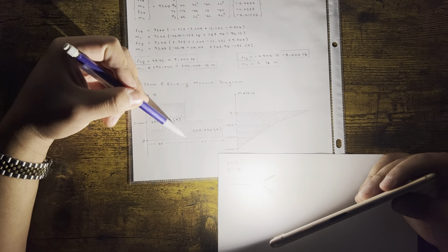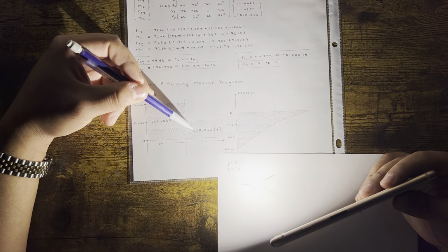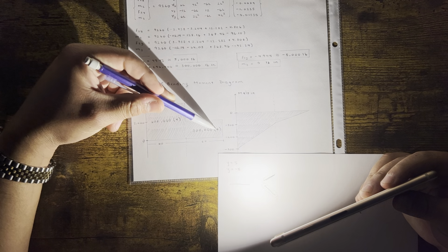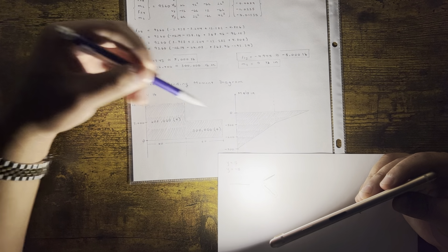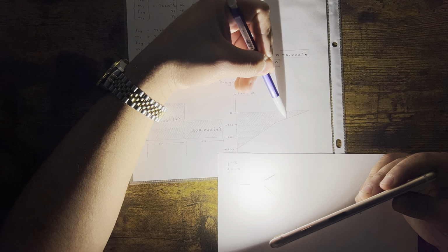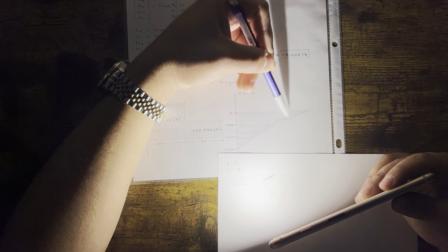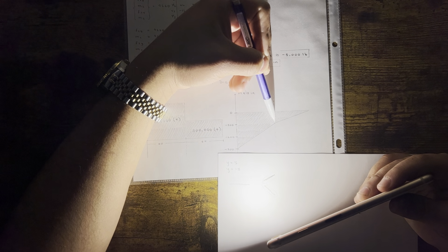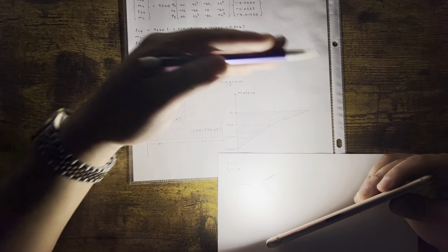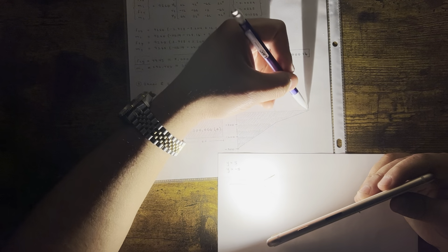And then once you get to that part of the beam, that 300,000 is also going to push you up, but at a slower rate. So now we're going like this. It's still going up, just not as steep. It's more flattened out, and you end up at 0. And that is how you do the bending moment diagrams and the shear.